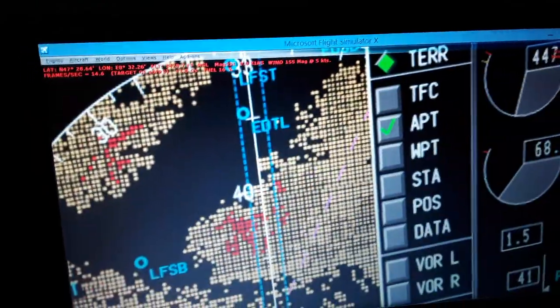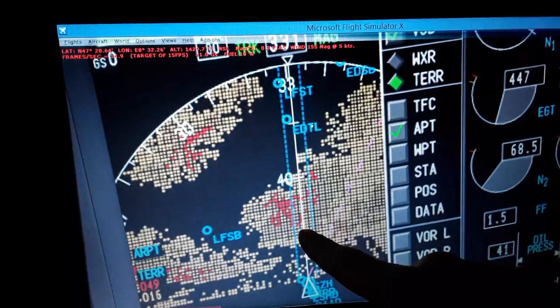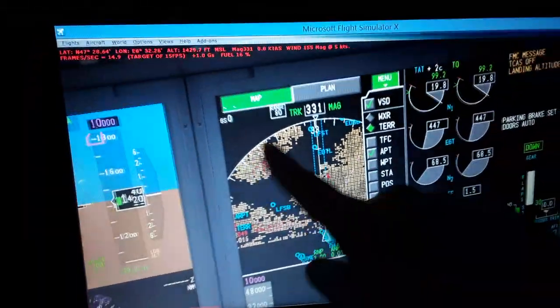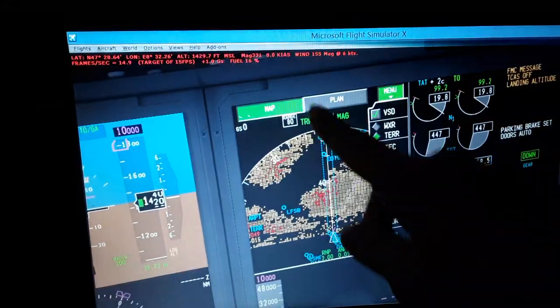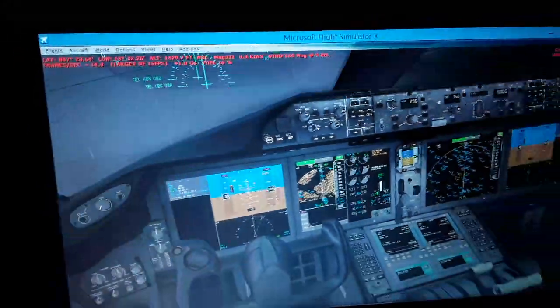You can see the aircraft position, 40 nautical miles to 80, the distance and also the degrees. Over here is the magnetic North Pole right now displayed versus the geographic North Pole. So the navigation display also displays the terrain map with the airports. You can see where the airports are located, the distance away from your aircraft. You can see the airport that we use for takeoff and for landing. You can see the runways and the taxiways we use, the runway length, and also the heading of the runway for takeoff and for landing.